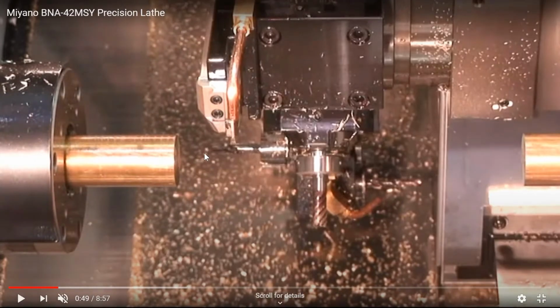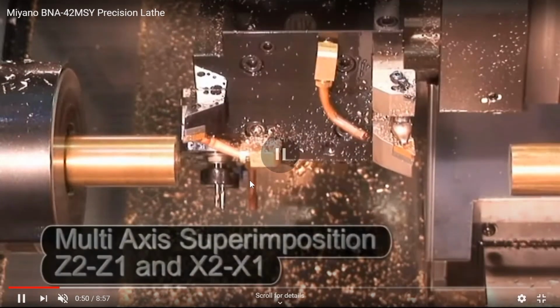Basically, over here we have the stopper, which extends the bar. In this situation, I stopped the video, we have one station where the tool is on the main spindle, spindle 1, and we have another that is on spindle 2. In this moment, you can, or you don't have to, run it in superimposition mode. In this video, it is in superimposition mode. What is very important to say for this machine is that the sub spindle cannot go beyond the X2 axis.